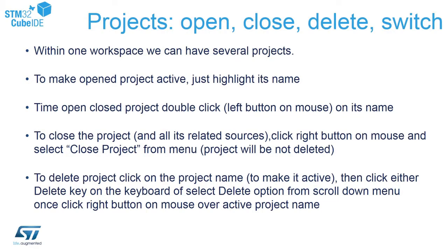Projects. Within STM32CubeIDE, as it is an Eclipse-based environment, we are working on a workspace which can contain one or more projects. Within the workspace, we can perform some basic operations on the projects. We can switch between them, we can make them active or inactive, we can close a project, we can delete the project, and we can delete the project from the file system as well. So all of those features are available.